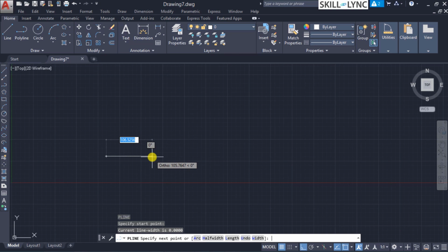And also a key point to be noted in the polyline is that this polyline once created can be edited and converted into a spline, that is a smooth spline if required. So that will help us to draw a contour profile kind of thing that will be useful in your advanced drawings. So a key characteristic of this polyline to be taken note of is that it can also be drawn with dot, dash or complex linetype commands. That is, you can edit it with the line property.